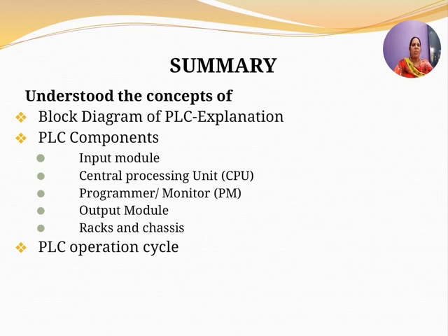Then we are left with the operation cycle of the PLC. The PLC can be easily understood as a cyclic scanning method known as the scan cycle. The steps followed in the PLC scanning process: the operating system starts cycling and monitoring of time. The CPU starts reading the data from the input module and checks the status of all the inputs. The CPU starts executing the user or application program written in relay ladder diagram or relay ladder logic or any other PLC programming language.